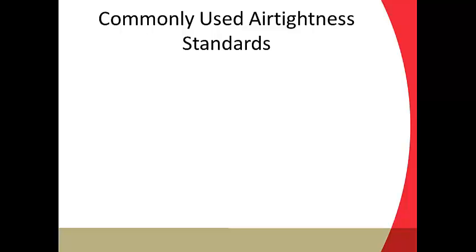And how the test should be performed, if you're just testing it at 50 pascals, how you take a baseline, how long a period it needs to be, how long the periods of record at each data point need to be, and then how to calculate the accuracy and repeatability of the test. So standards get pretty involved.